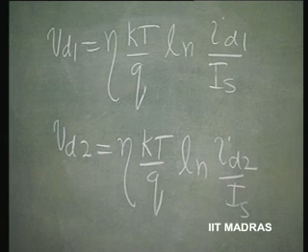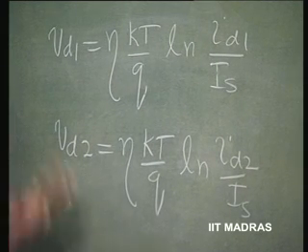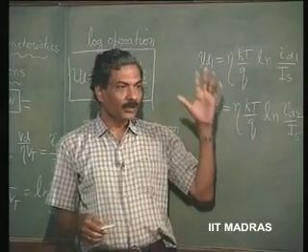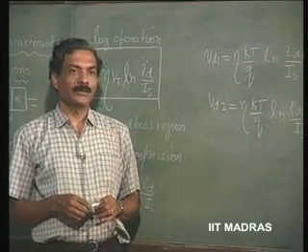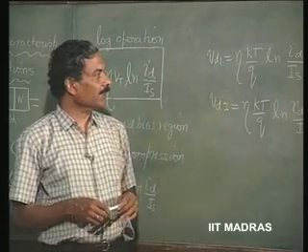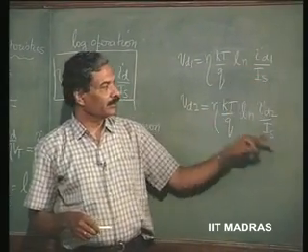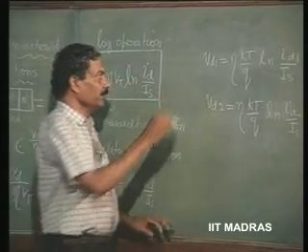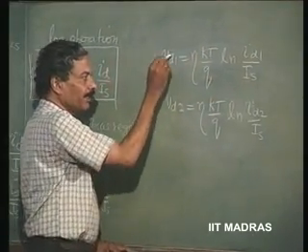Such a feature is possible in all integrated circuit components. You subject the diodes manufactured to the same operating conditions, the same sort of temperatures and the same process conditions, etc. So, the manufactured diodes have Is perfectly matched. Then if they are operating at two different currents, the voltages will be Vd1 and Vd2.